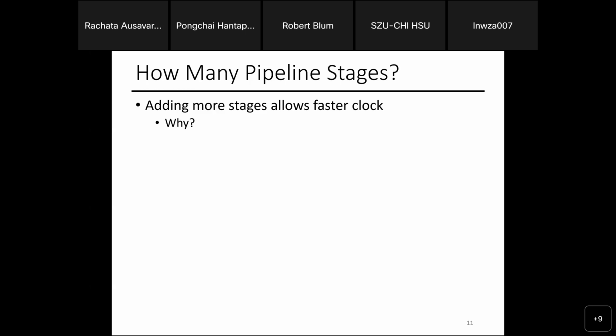Am I reading 1 byte? Am I reading 5 bytes? Am I reading 4 bytes? That part alone likely costs one cycle, because you need to read the first byte, then figure out how many more bytes am I reading, right? So in that case, decode makes sense to have multiple clock steps in the middle and have multiple stages, right?